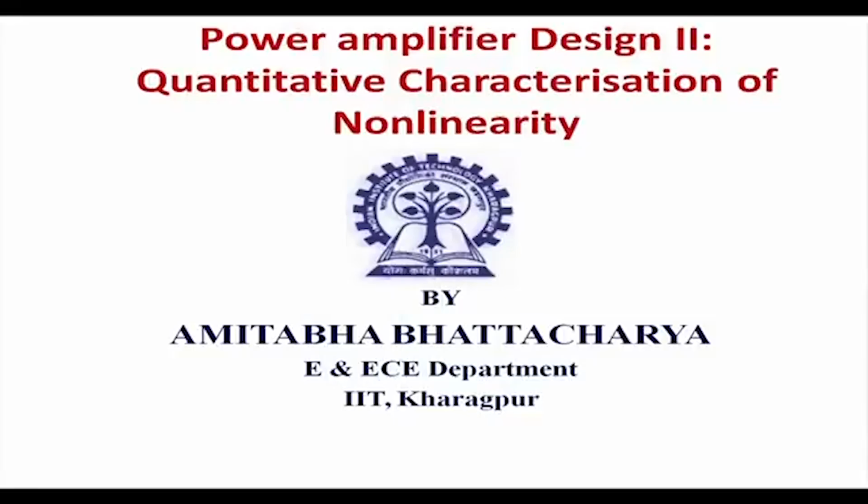Welcome to this second lecture on power amplifier design 2. We have already seen the nonlinearity, its effect that it creates third order intermodulation product. Now, we will quantitatively characterize that third order intermodulation product in this lecture.